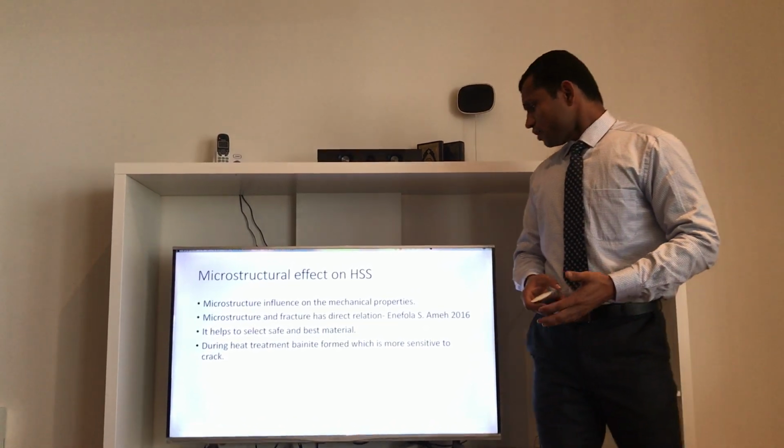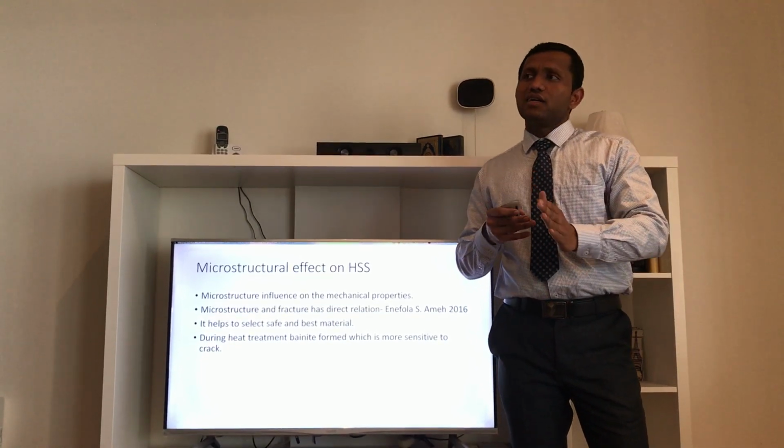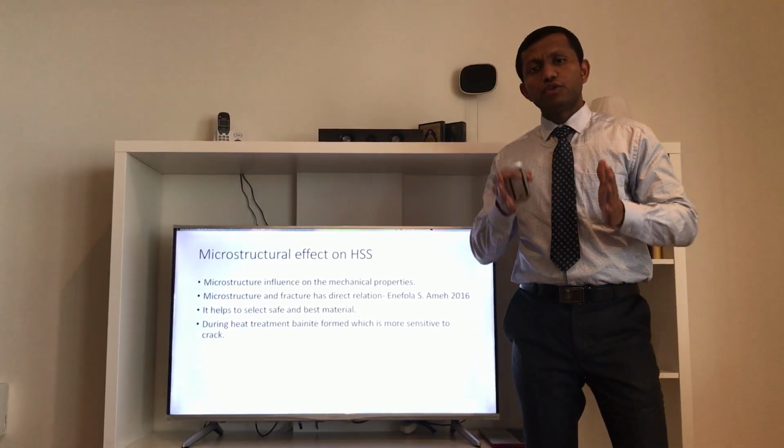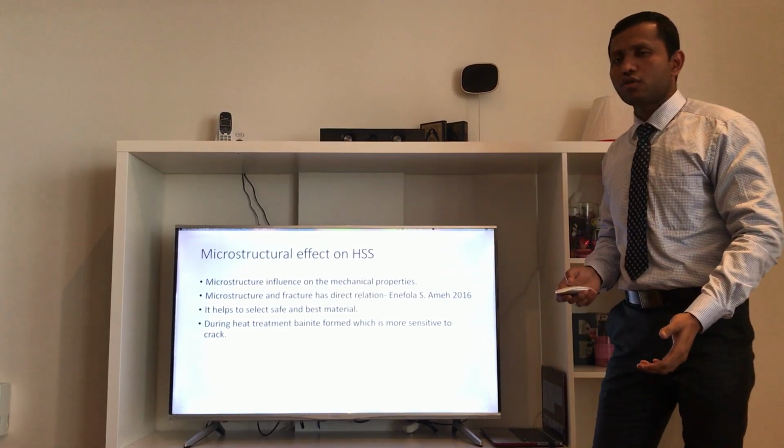Even during the heat treatment process, if bainite formation is there, it is more sensitive to cracking. So we should take care of the microstructure of the specimen as well while choosing high strength steel.